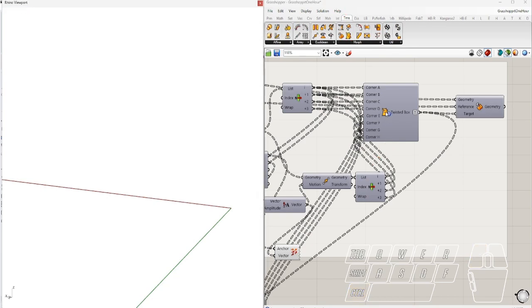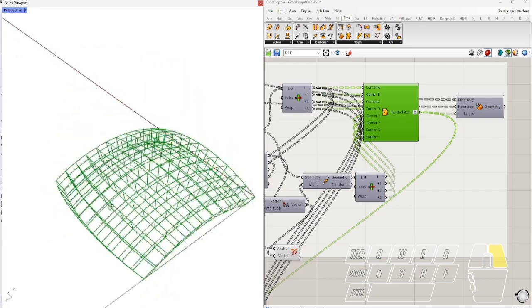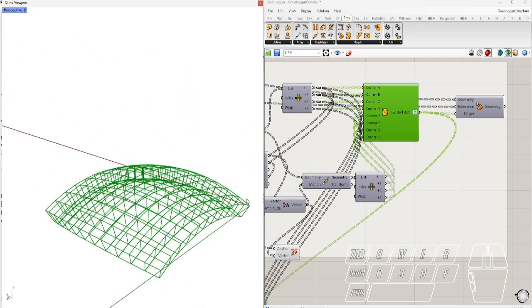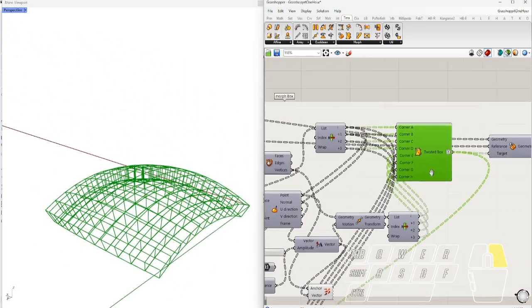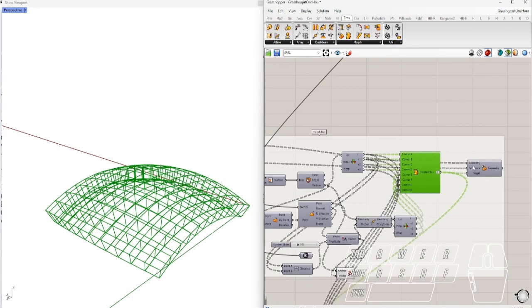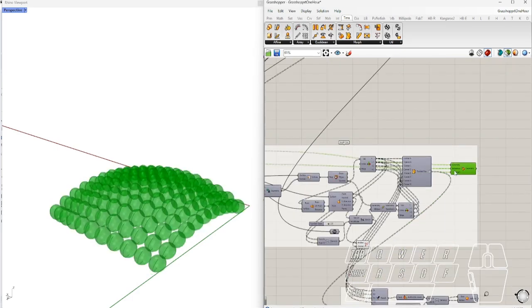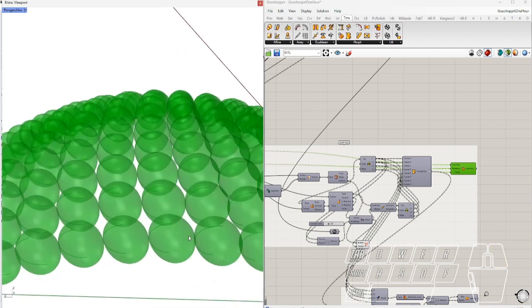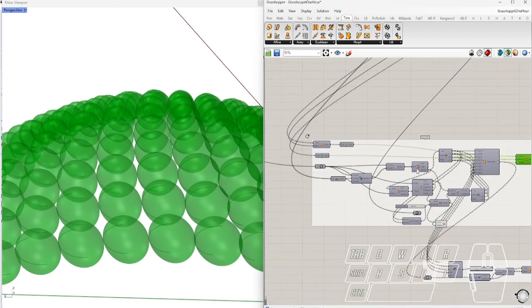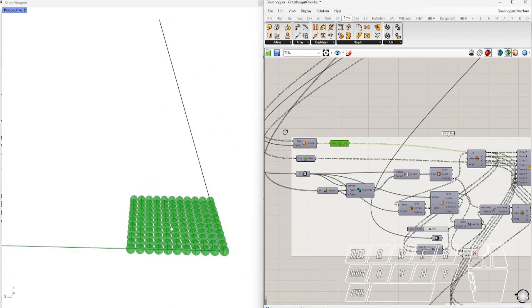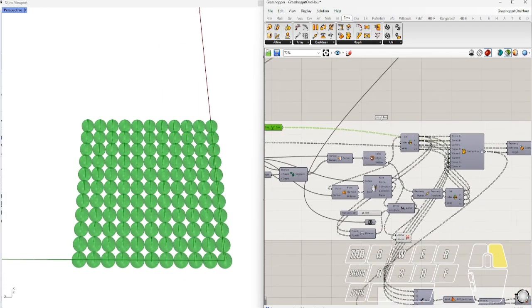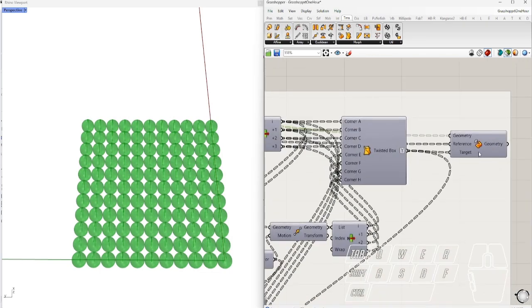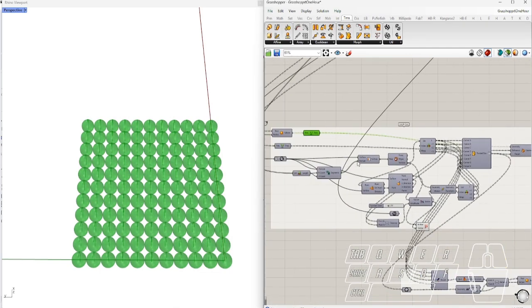So I will morph first the spheres. You see, the sphere is distorted. It's not a good sphere. It's not a perfect sphere, which is something we don't appreciate much. So there is a trick: to pre-use the twisted boxes to generate spheres inside them with a fixed radius. And now I'm gonna show you how I'm gonna do that.